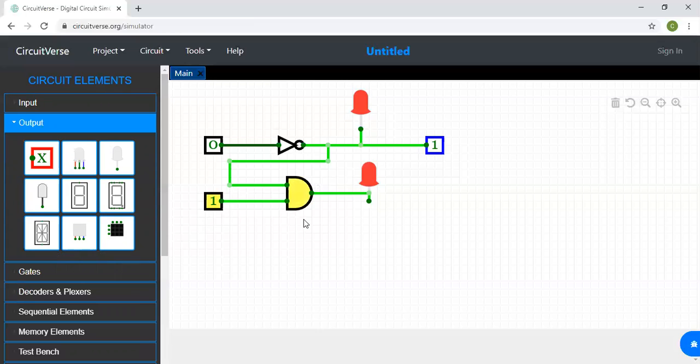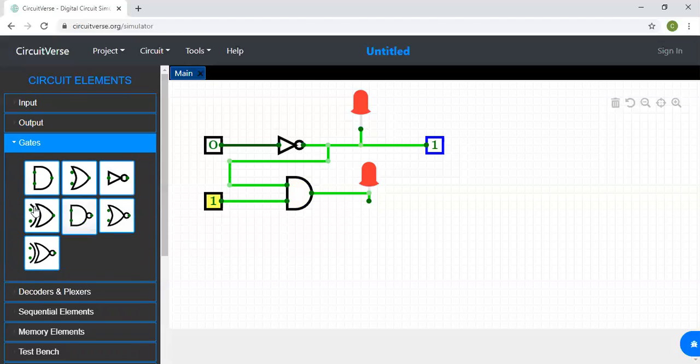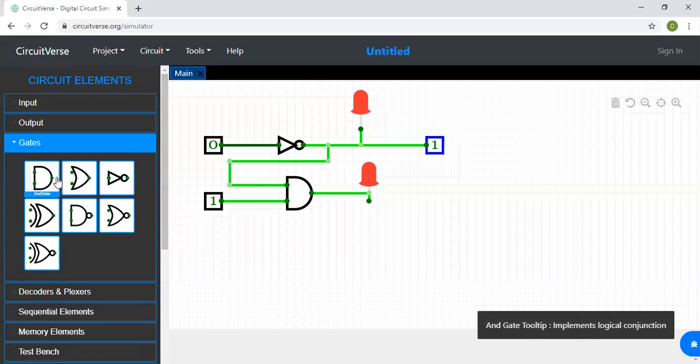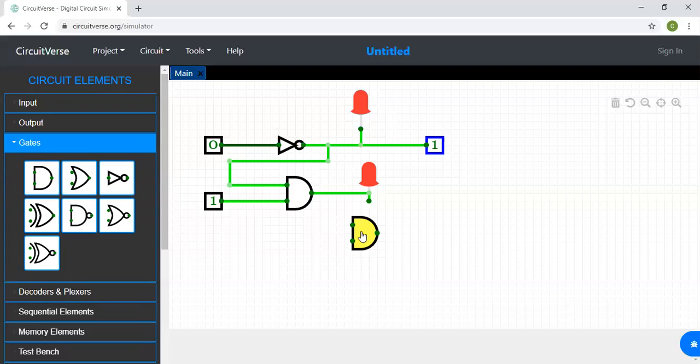So as I was saying, we have fan-in, the number of inputs. Let's say we wanted a 3-input AND gate. How could we do a 3-input AND gate? Well, if our fan-in is just 2, then I would have another AND gate come in. And then let's do some text. I think we can write out text.